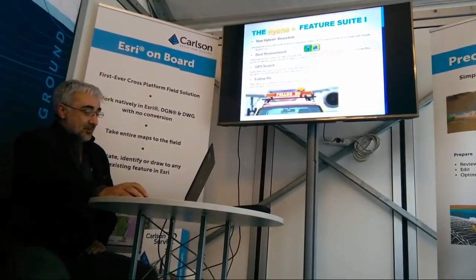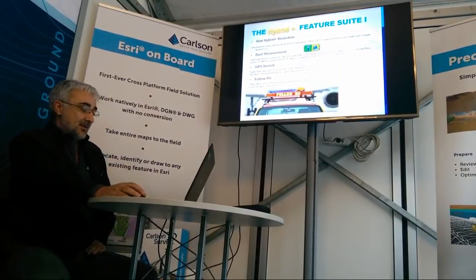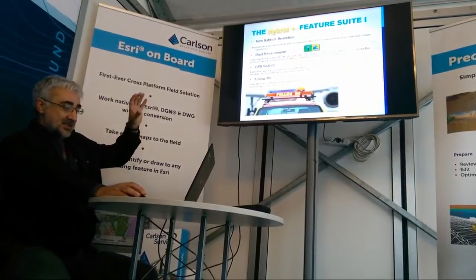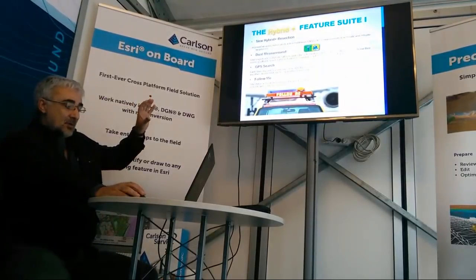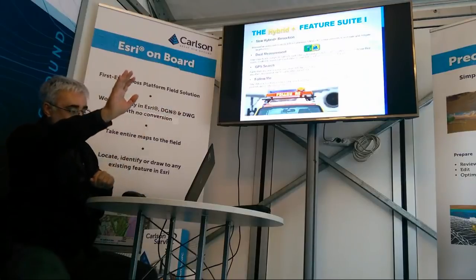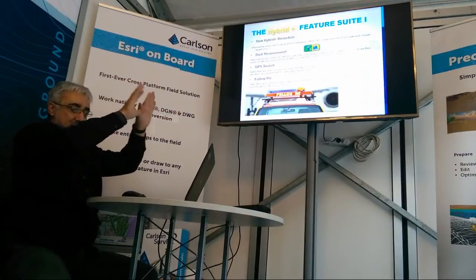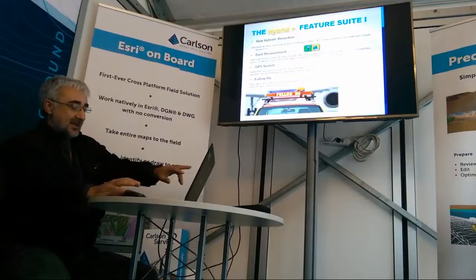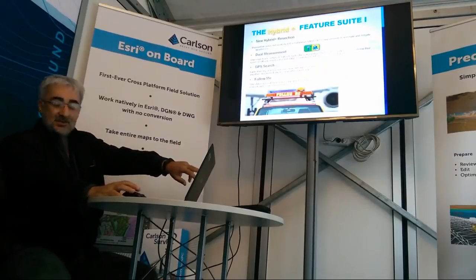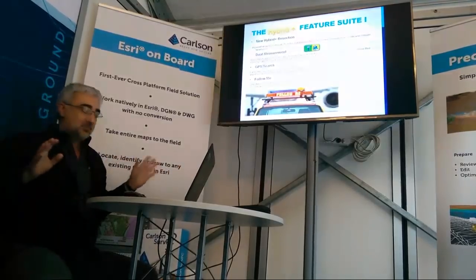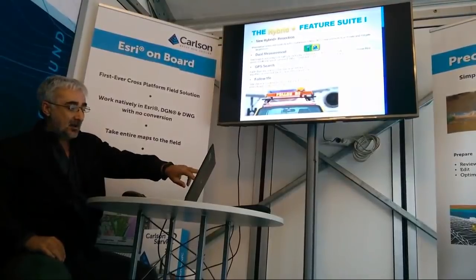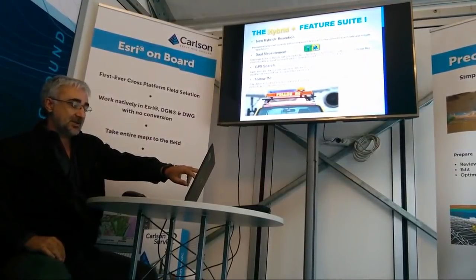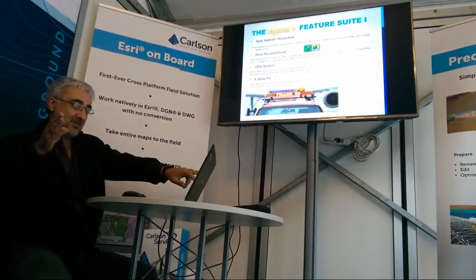Next is the dual measurement. We have this instrument icon at the top that is new in version 6. It will work standalone for GPS, total station, or hybrid, showing the two instruments. Colors mean something. Red means no connection at all, no Bluetooth, nothing. Yellow is different depending on total station or GPS. In total station, it means you are not locked to the prism, you cannot measure.